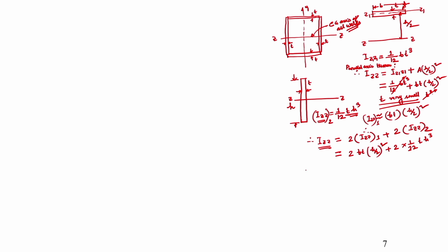Now, this ZW, what does it mean? I have already told you, ZW is equal to IZZ divided by throat thickness into Y, where Y means here h by 2, always you should keep it in mind.